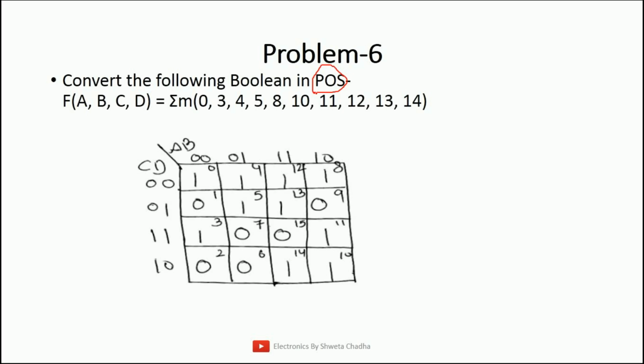Let us start grouping. Starting with grouping of 16, not possible. Grouping of 8, not possible. Grouping of 4, that too is not possible. Grouping of 2, yes, that is possible. Here comes a group of 2. Here comes a group of 2. And the final one, here comes a group of 2. So the answer is 3 groups are sufficient for grouping zeros altogether.